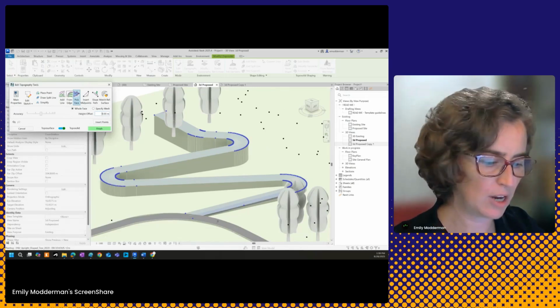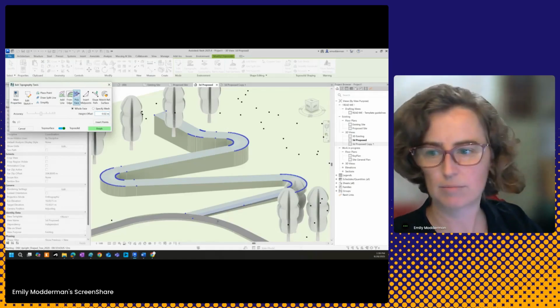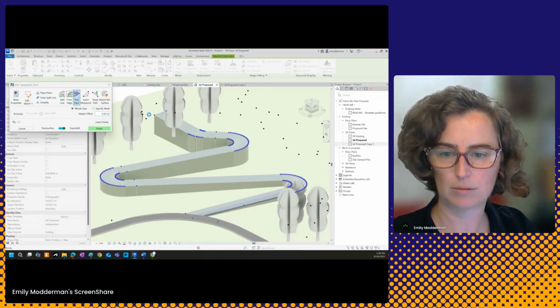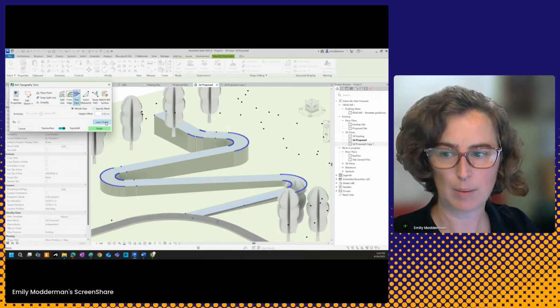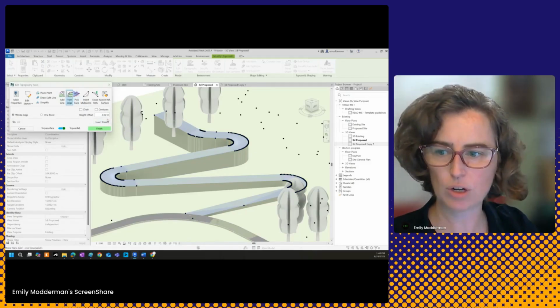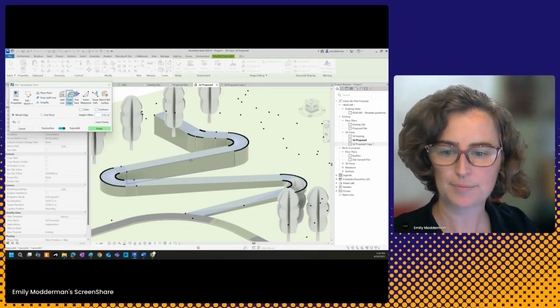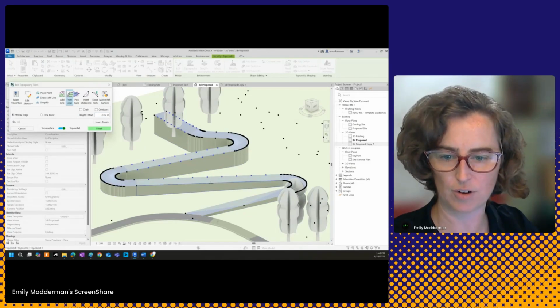And I want my points to have a slight negative offset. So I want this surface to come up to just a couple of inches below the edges of this surface. I'm going to insert points. And just because I know what's going to happen here, I'm also going to use from edge, and I'm going to set the same offset, -0.02. And I'm going to pick these straight points just so I get a little more information along those straight points, because from edge, or face, doesn't always get me that.